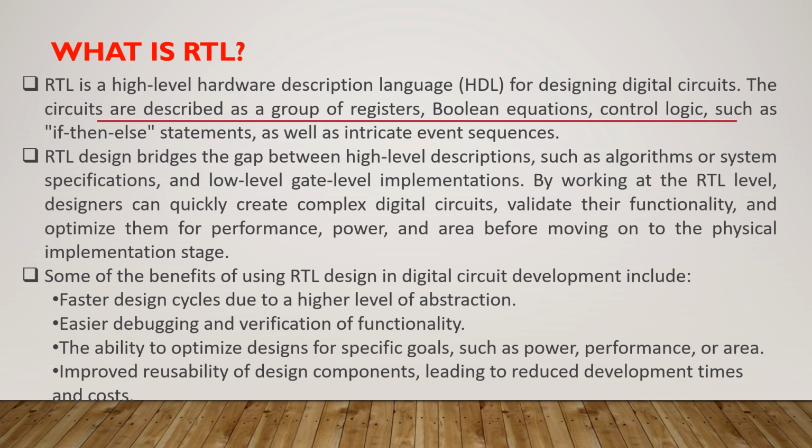In RTL, the circuits are described as a group of registers, and also Boolean equations, control logic, everything is used in the RTL design. RTL bridges the gap between the high level descriptions, such as algorithms or system specifications, and the low level gate level implementation. So it is a bridge between these two. By working at the RTL level, the designer can quickly create complex digital circuits because we are dealing only with the registers, not with the actual structure of your design in terms of gate levels.